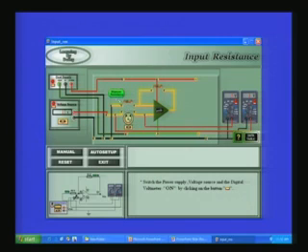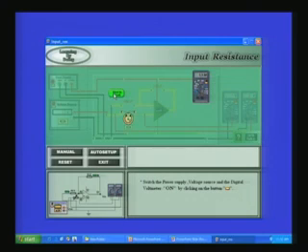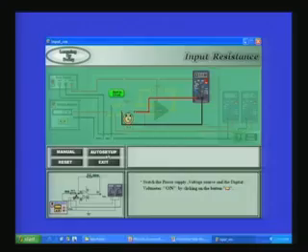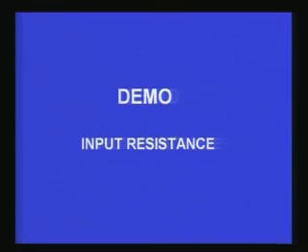So in order to measure, I will just go to measure with resistance. You see that it is disconnected from the circuit, and the resistance is measured using another multimeter, and it shows around 5.1 megohm. So 5.1 megohm is the input resistance by this half deflection method. That is what we have now measured. So having seen this, let me quickly go on and show you an actual measurement on the laboratory table.